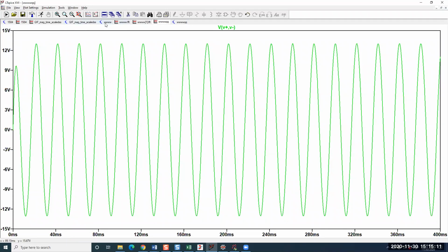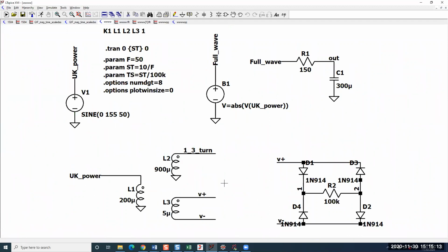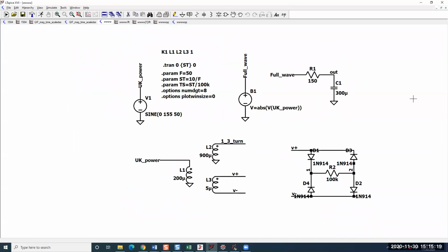So now this signal we could actually put into this filter, but it doesn't quite. There's issues with that in that if you attach anything to it, it changes the time constant and thus changes practically everything. So what we have here is a full wave rectifier.